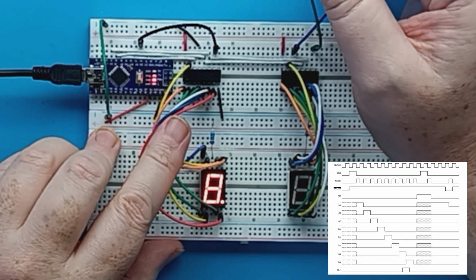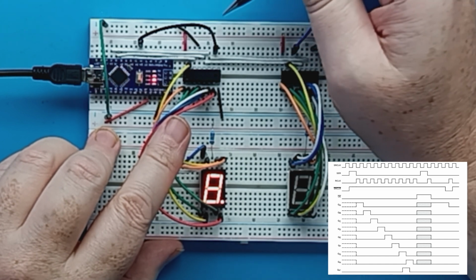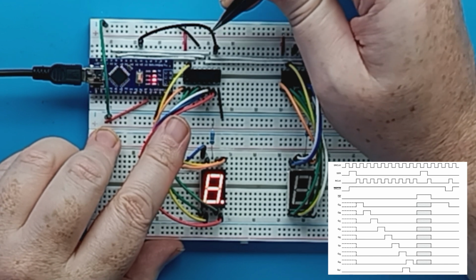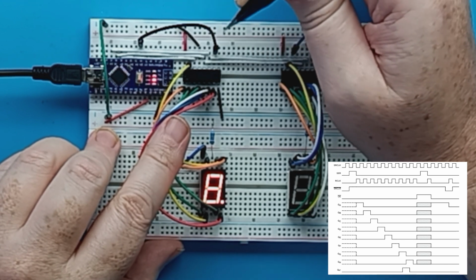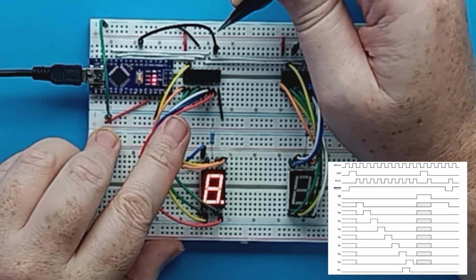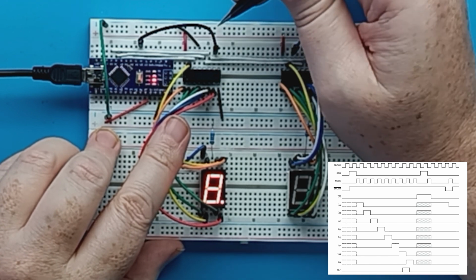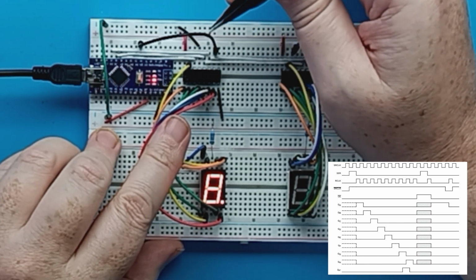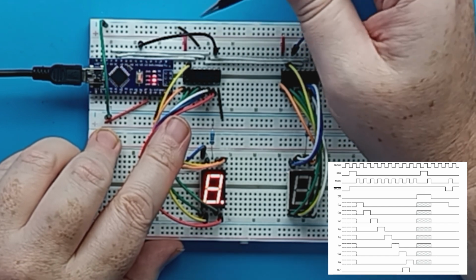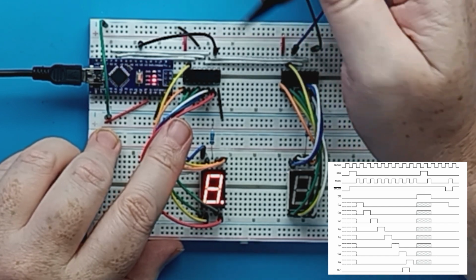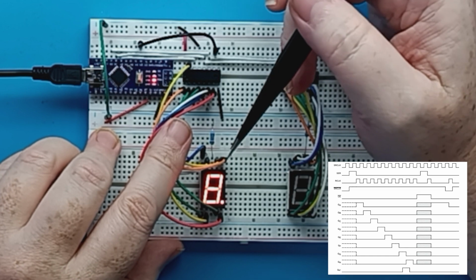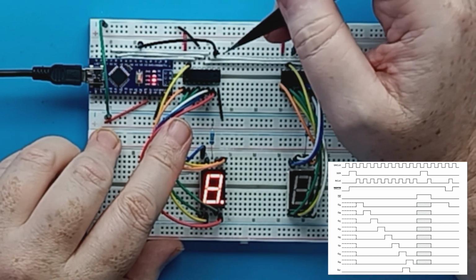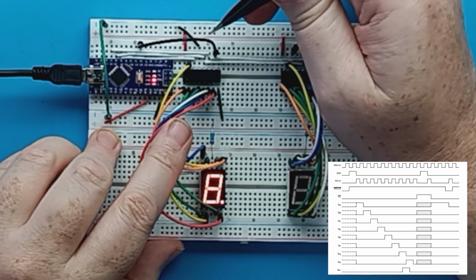Now, some things to watch out for are to make sure that any outputs that you're not using are actually tied to the appropriate ground or VCC. You never want to leave any of these pins, inputs or outputs, floating. If you do, you can get some weird results. The other thing I noticed with this chip is the reset line.